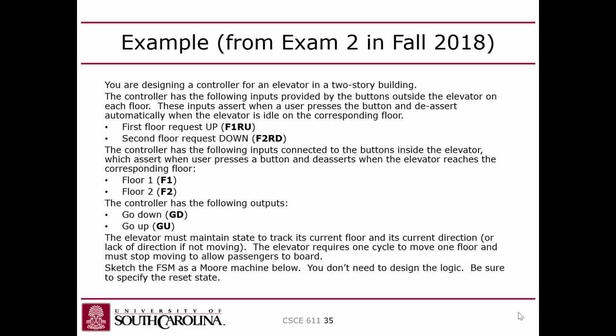How are the following inputs connected? Sorry, I screwed that up too. This is F2RD here, and this is F1RD, because those are the ones outside the elevator, and the ones inside the elevator are floor 1 and floor 2. But those would actually work the same way, because if you're on the first floor and you push floor 2, so this would be OR floor 2, and this would be OR floor 1. There we go. Now we got it.